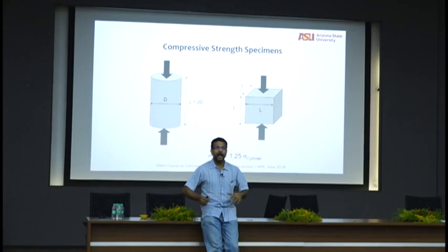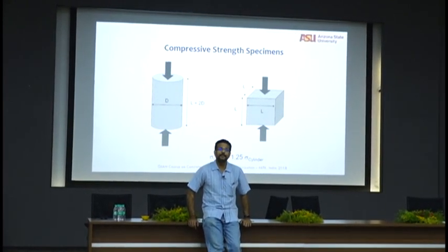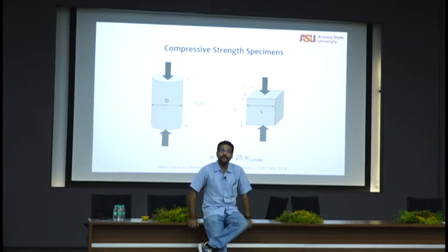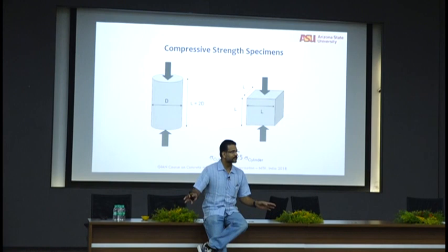Take the alkali content of cement. We'll say that you have to reduce the alkali content, especially with a lot of alkali reactivity. We have been pushing for a 0.5% alkali content. Cement companies will never allow that, they want to make it 0.85. So you come to a compromise of 0.6. Neither here nor there. All standards are neither here nor there.